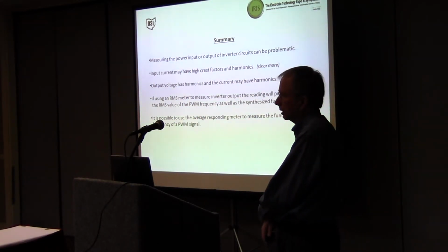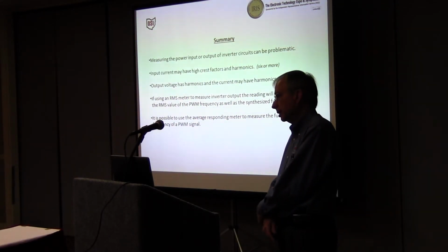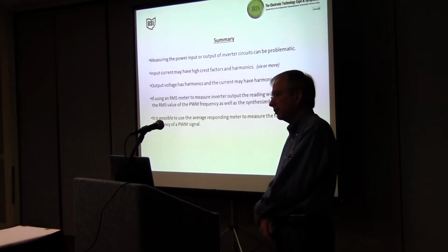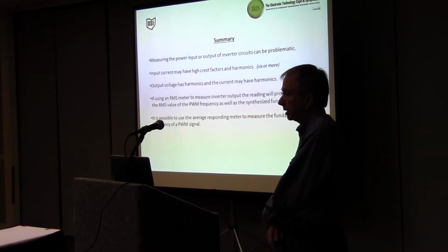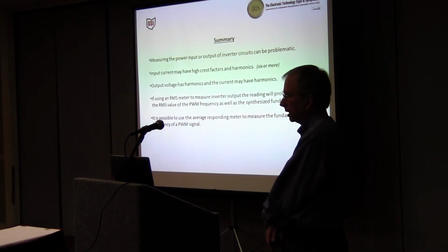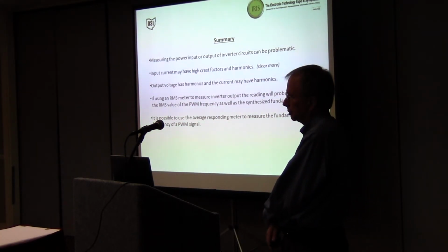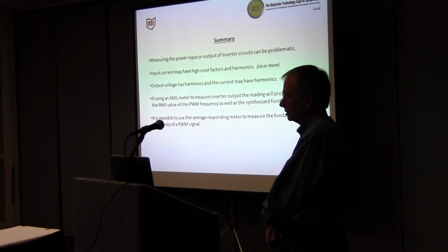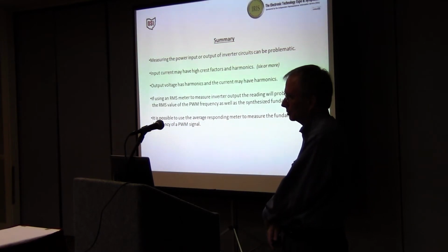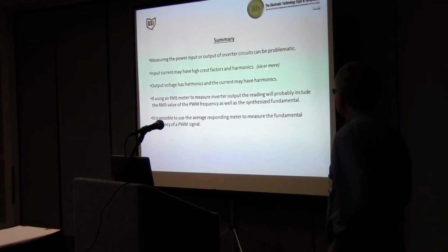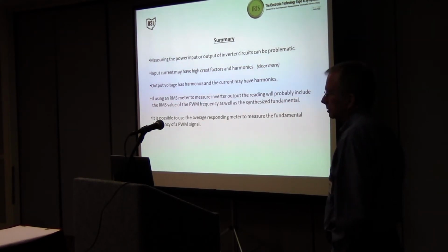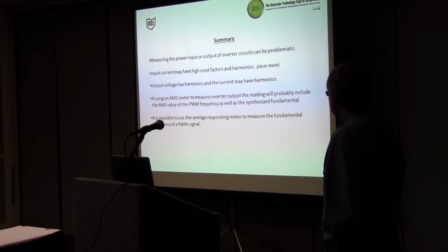To your point, depending on the load, the current may have the harmonics filtered out because of the inductive nature of the load. The voltage typically will not. In fact, they get almost amplified because the inductive nature of the load tends to give voltage kicks and things, and even makes the voltage waveform even harder to control. Crest factor can be up to six or more. This can be a problem.